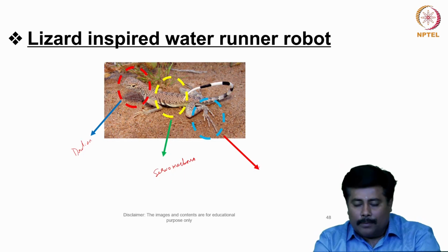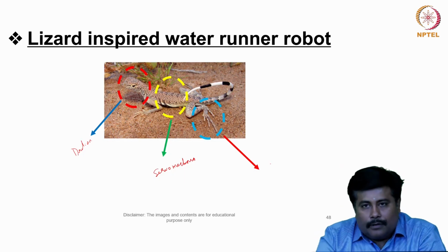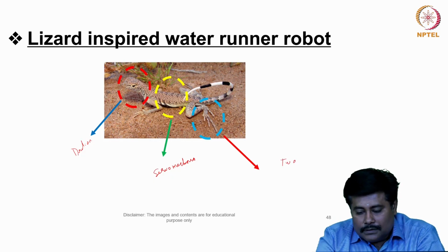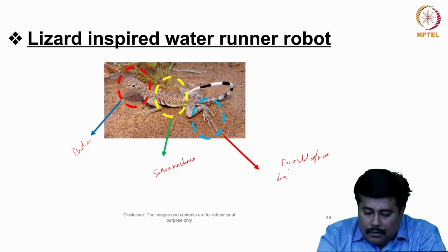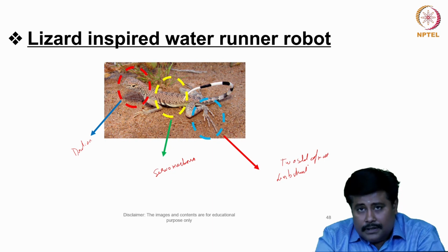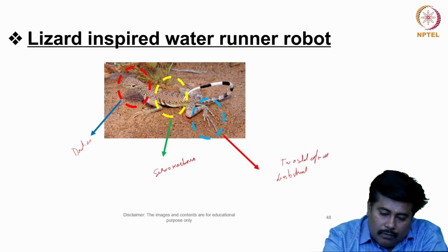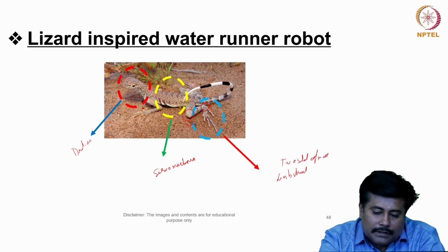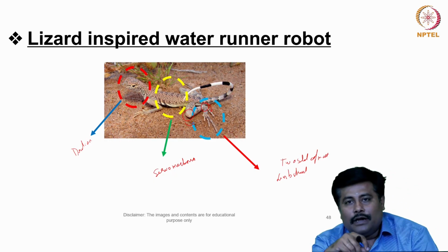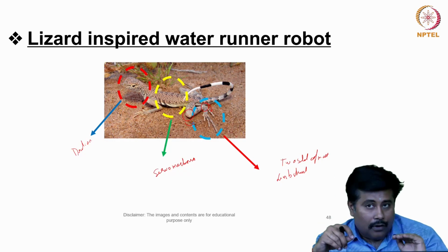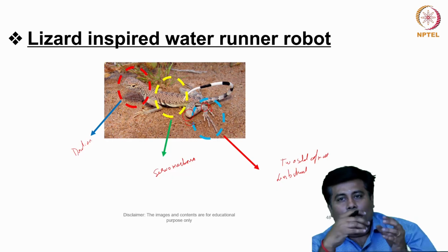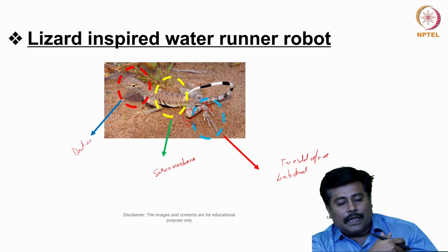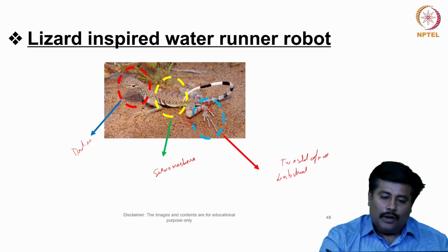This direction mechanism will take care of the overall movement of the structure, and this structure more talks about the overall load capability. From the load capability point of view, we can have two sets of motors catering to the limb structure. In this limb structure, one set of motors caters to this particular movement and the other set caters to the other movement. Appropriately, we can have a theta orientation over here. This theta orientation gives the load acting on the load bearing motors, so that the load can be easily calculated.